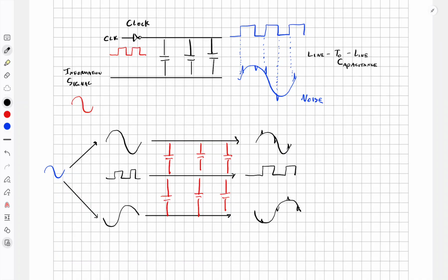But the important thing is that there's a way you can convert this two-ended output back, combined together, into one signal. And when you do that, yes, the clock signal did create noise in the two equal and opposite signals, but because it pulls on them equally, when you recombine the two signals together on your output, the noise cancels out.